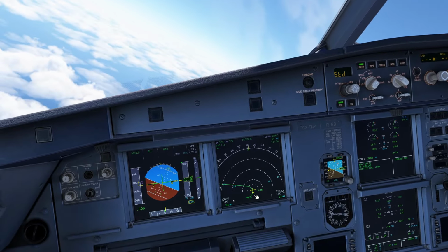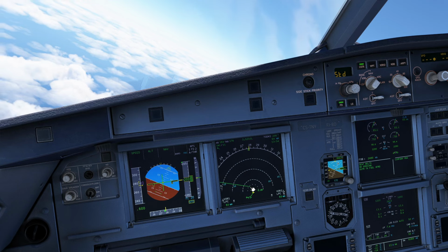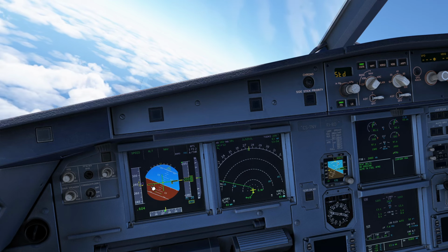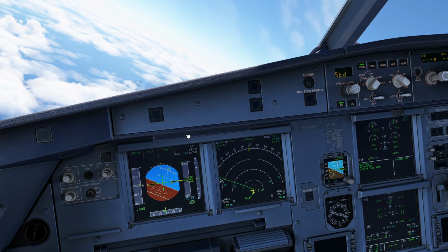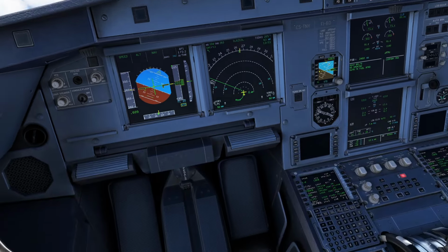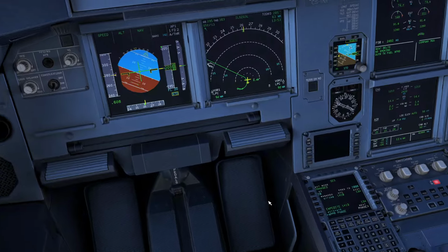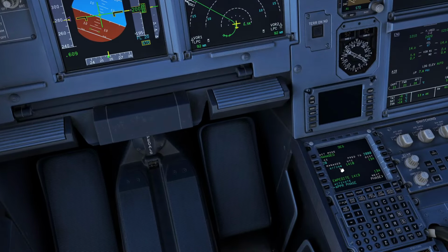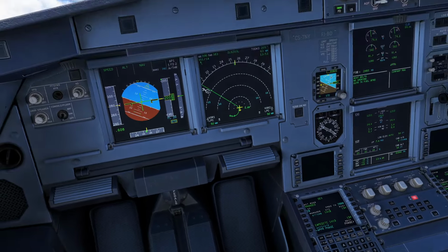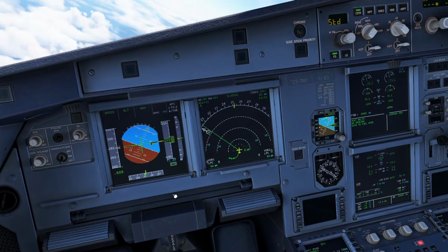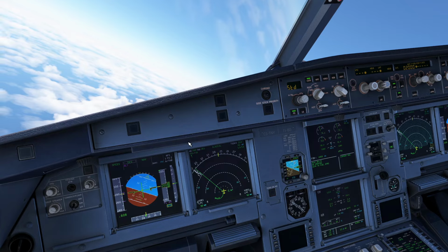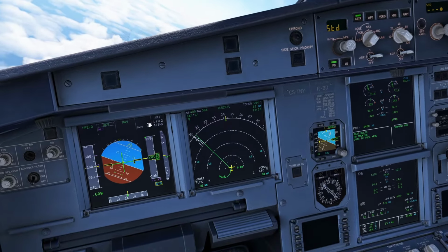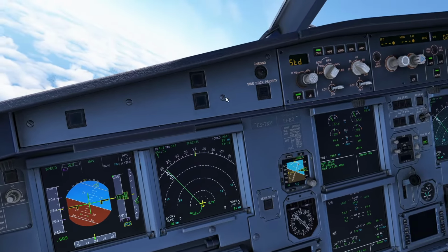You can see we leave the holding and we are out of holding. The speed of the aircraft increased to managed speed, which should be observed in the descent section, as you see 280, and the green dot speed was the holding speed. Okay, set the aircraft selection for descent.